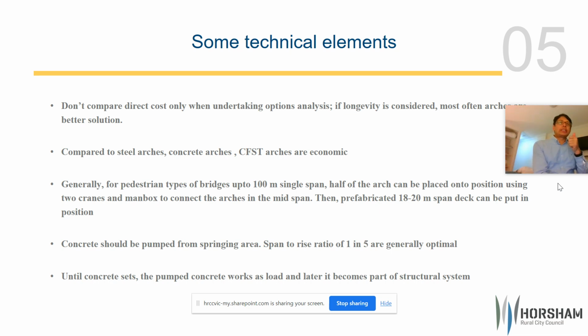You need a good geometric nonlinearity analysis, and that is the only way to account for it, because there are not many formulas available to determine whether the structure will fail in buckling or whether geometric nonlinearity is a problem. As I said, from the static analysis, it's not always a problem. The main problem is always not material failure, it is the buckling failure.